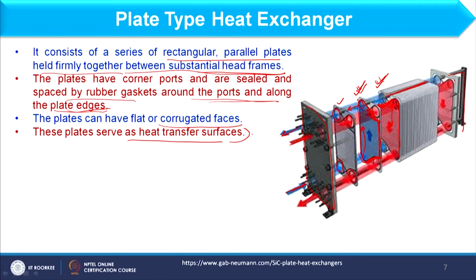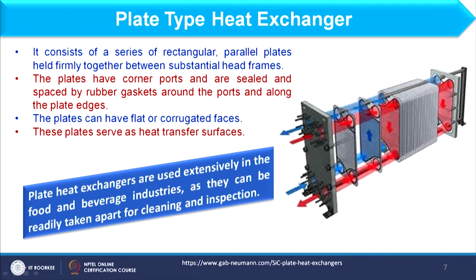So this point we have already discussed. As far as the utility of plate heat exchangers is concerned, these are used in the food and beverage industry, as they can readily be taken apart for cleaning and inspection. Now, as I have told you, two plates are very compact or very close to each other, which means it has a very high tendency of scaling. To avoid that, plate type heat exchangers are usually used for clean fluids, not fouling fluids. So that is the main point about plate type heat exchangers.